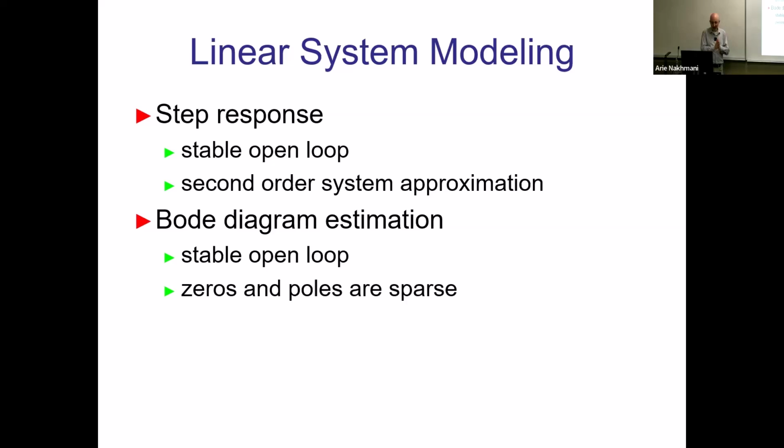Now, given that phase and amplitude, you can plot Bode diagram as a function of frequency. So sweeping the frequencies as input, measuring frequencies as output, and all of their amplitudes and phase changes from the input. And this is exactly what Bode diagram is. The ratio of amplitudes, input and output, and difference in phases between input and output. Okay, these are the two plots of Bode diagram.